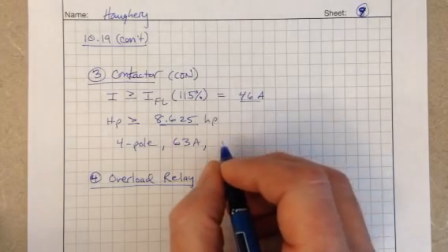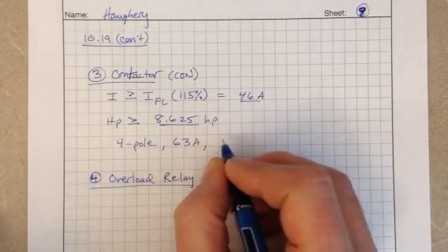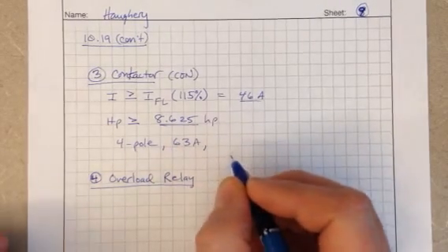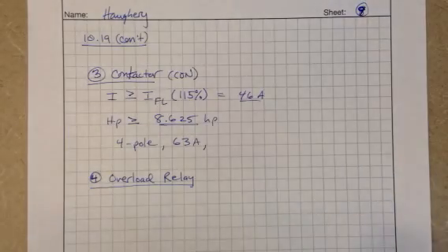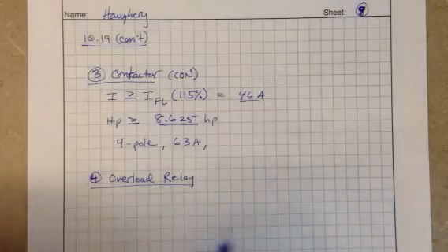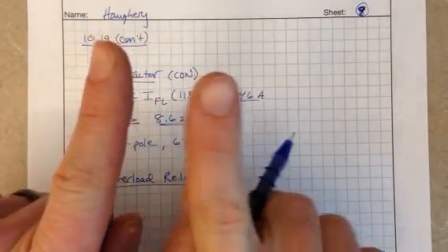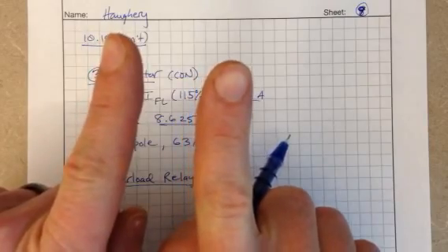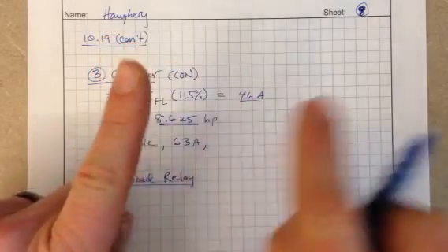And then a coil voltage. Contactors have a coil that you use to energize. You put power to the coil and they close. So the contactor is open, you energize it, it closes, and current goes through it.